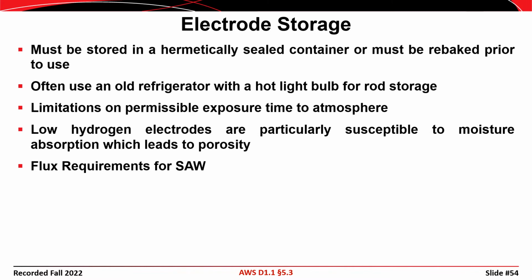So it's important to keep the electrodes sealed until you're going to use them, and then after you've opened a sealed container, make sure you store them properly so that they don't absorb moisture. Typically, you'll see an old refrigerator with a light bulb inside of it. The light bulb keeps it warm in there and keeps the humidity low inside, and that works pretty well for storing electrodes.